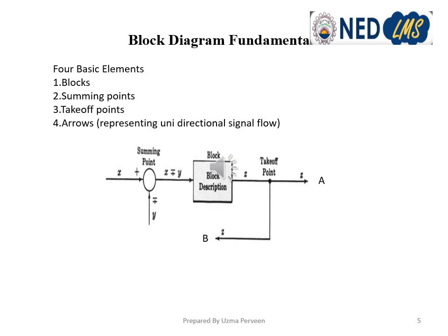Any specific configuration of the block diagram may have these four elements. These four elements are blocks. Blocks are the main points in which the transfer function is written, sometimes in words or sometimes in mathematical form. When we use block diagram reduction techniques to find the transfer function of a block diagram, or we want to model our system by the block diagram, usually we use S-domain transfer functions within the block of the block diagram.